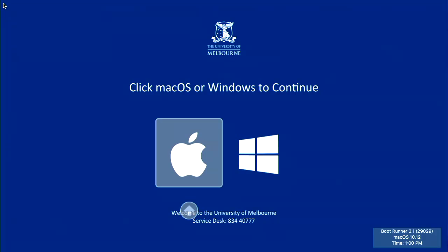Yeah. So this one is mainly used for communicating signals, because when your signal is coming, this voltage will decrease, and when the signal is not there, this voltage will increase, so that you can get a pulse. You know what I mean? Depending upon the application, whether DC or AC signal is passing through, you will change the connections accordingly. So the exchange is through an optical process. No electrons are flowing. That's the reason we wrote that here.